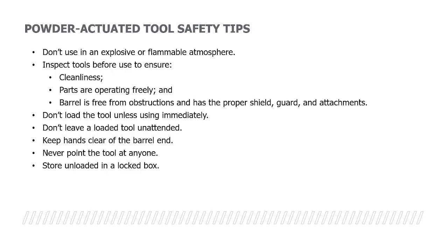The barrel should be free from obstructions and have the proper shield, guard and attachments in place. Don't load the tool unless you're using it immediately, and do not leave a loaded tool unattended. Keep hands clear of the barrel end and never point the tool at anyone. Make sure you store it unloaded in a locked box, is what we want to see. In other words, it shouldn't have any type of power source inside the powder actuated tool.